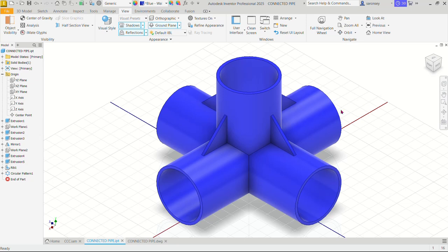We would first of all extrude this pipe. Then we would offset a plane where we would create a sketch so we can extrude this feature. We would then mirror it on the opposite side. Finally, we would create this feature that sits on top of the base model, and then we would create our ribs. Let's go ahead and begin with today's exercise.